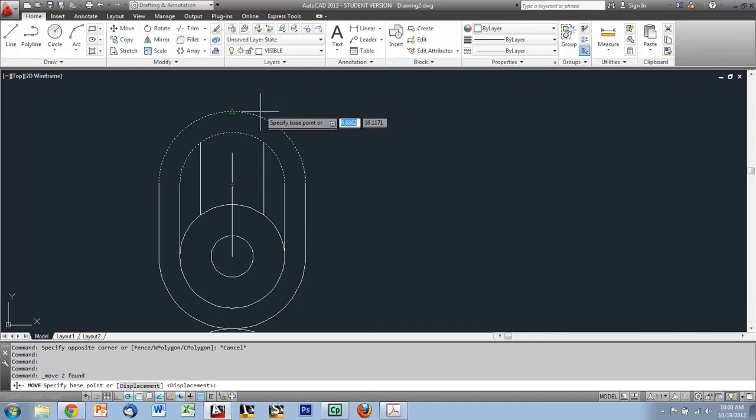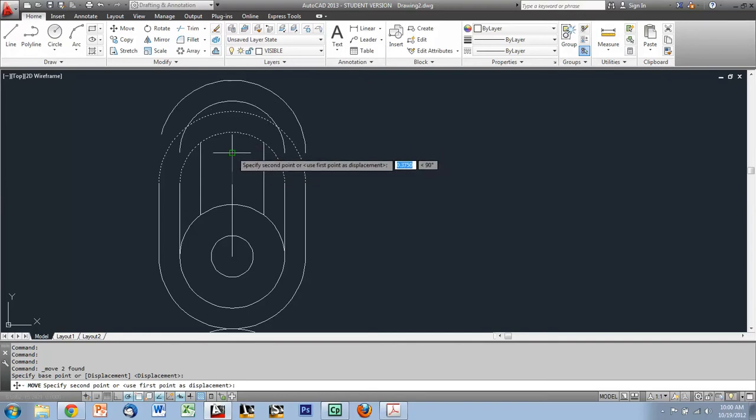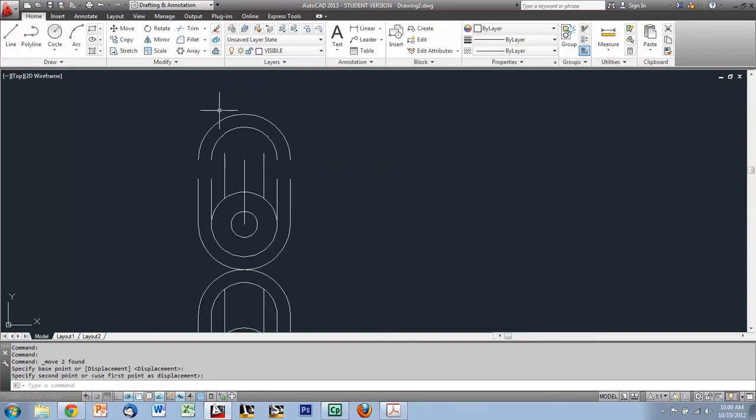and I'm going to hover over the outside of one of them so that I can O-snap to the center point. So you'll see my center O-snap pop up, and I'll click that. And I want to take that center point and move it up to here, to the end point of the line that we just drew. So I'll click there. And now we know that our link is the right length.